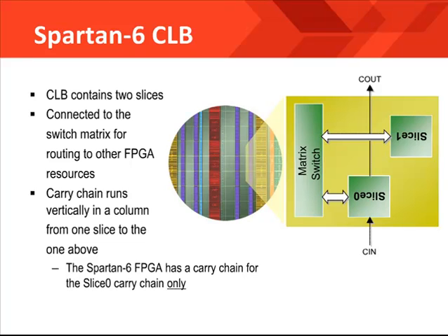All Xilinx FPGAs contain essentially the same basic logic resources, slices, which are grouped into configurable logic blocks, commonly called CLBs. These contain combinatorial logic and register resources. As you can see from this picture, there are a lot of CLBs on this die.